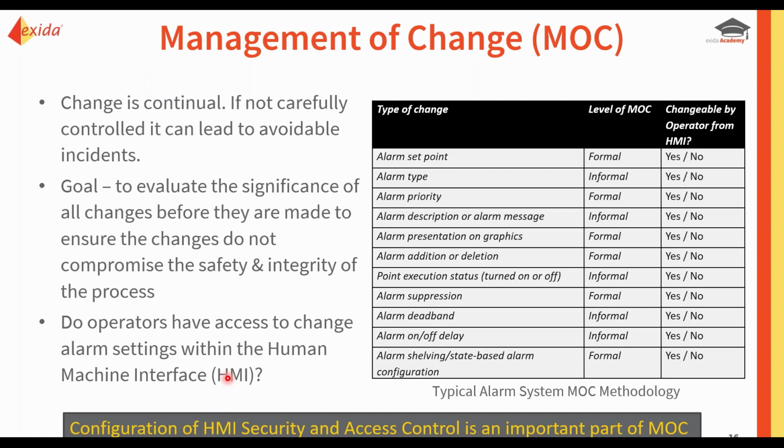Now, when it comes to management of change for alarms, we typically look at the type of change and perhaps set up a different level of MOC formality based on the importance of that type of change. In addition to that, though, we should also pay attention to whether the operator has the ability or the access to be able to change those parameters as well.